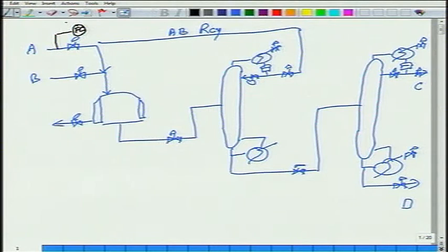Okay. So the set point, the fresh A feed rate is the throughput manipulator. Now once the throughput manipulator is set, I can go downstream as well as upstream from there. Upstream there is nothing, or whatever is there is not in my scope. I just have to go downstream now, right? So let's go downstream.